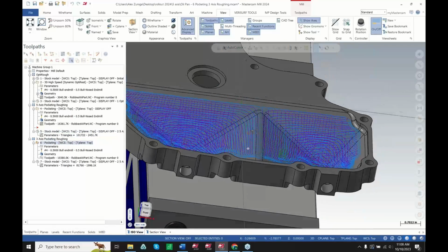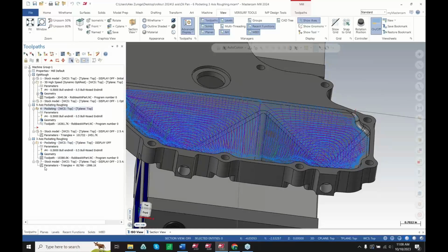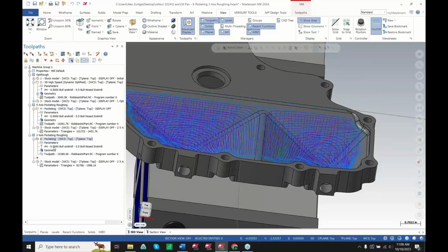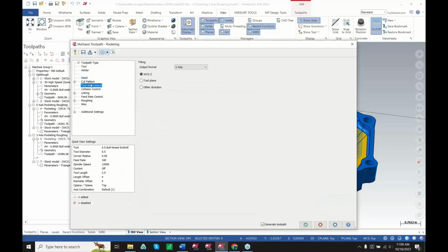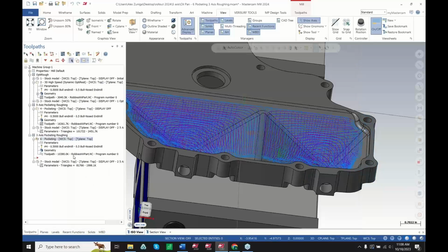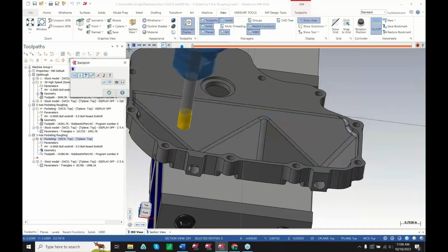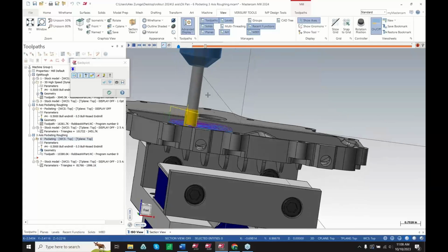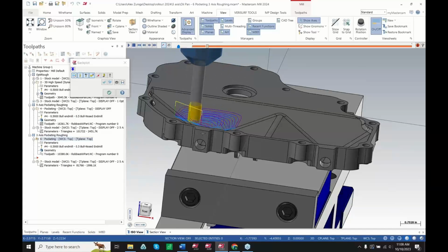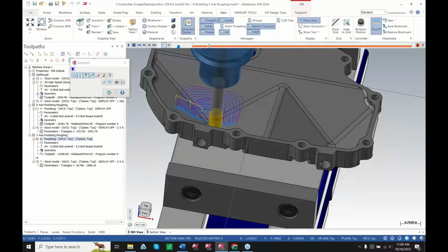We can still take this thought process that we saw in the original and turn it into a 3-axis motion. So in the tool axis control under pocketing now, we have the option to change this from 3 to 5 axis. Previous version, there was literally nothing here, not controllable whatsoever. So now when I run this toolpath, you can see it a lot more rigid because it's only moving in 3 axis. Same thought process, same dynamic motion, just in 3 axis.